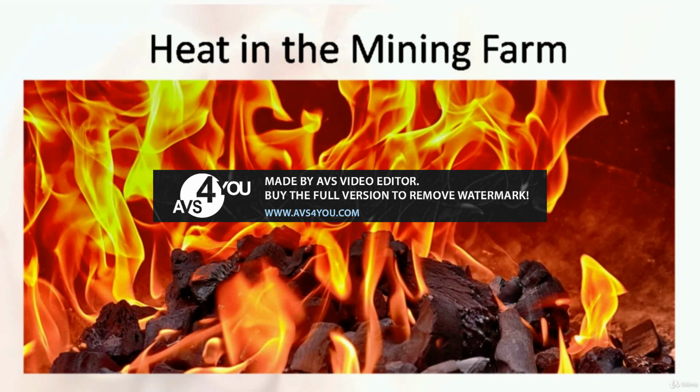The aim of the cooling environment for the mining farm is to transform the hot air that is exhausted from these rigs into cold air, which we can accomplish using a method called refrigeration. Refrigeration makes it possible to successfully pump the heat energy that gets generated from the mining rigs to somewhere outside of that space, particularly where it is cooler than the temperature inside the space where these rigs are situated.